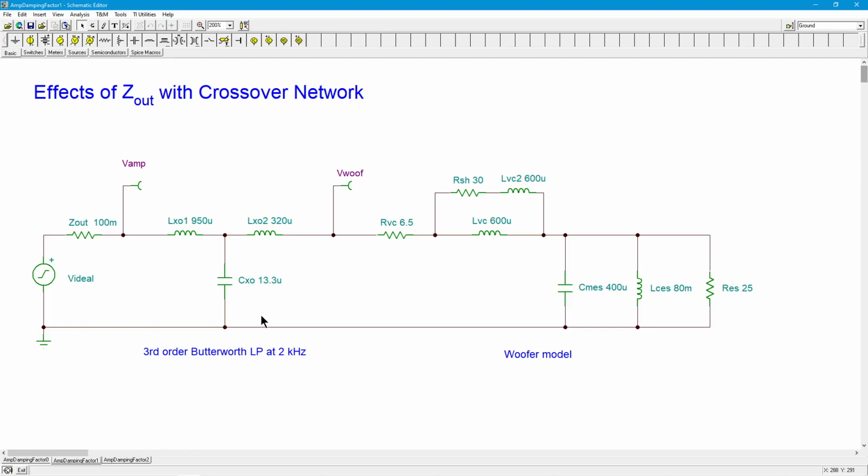Now, as I said a moment ago, you can get rid of a lot of these problems by just getting rid of the passive crossover and going to an active system. So you would have a low-level crossover, probably built with op amps, and then the output of the active crossover would go to separate power amplifiers that drive each of the transducers. In other words, if you have a three-way loudspeaker, woofer, mid-range, tweeter, there are 3 amplifiers. Yes, it's going to be more expensive, but it's a much better controlled system, lower distortion, higher amplitude outputs.